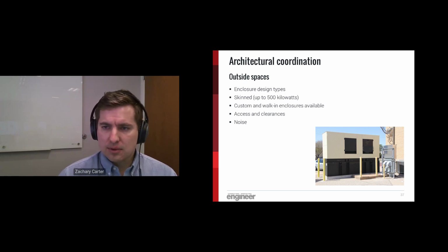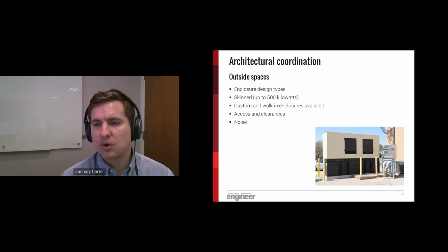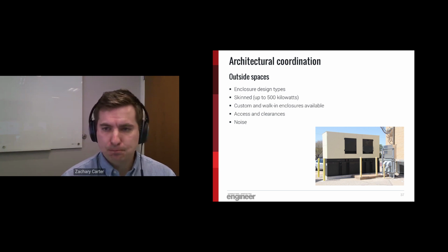You know, I think the thing with outdoor generators, again, is that physical security space. You maybe don't want to put this out in the middle of a parking lot where somebody could run into it, or you might want to conceal it architecturally. So certainly, there are pros and cons of both the indoor location and the outdoor location of your mission critical generators. We're hoping to highlight a few to consider for either scenario, indoor or outdoor, for you here on these slides.